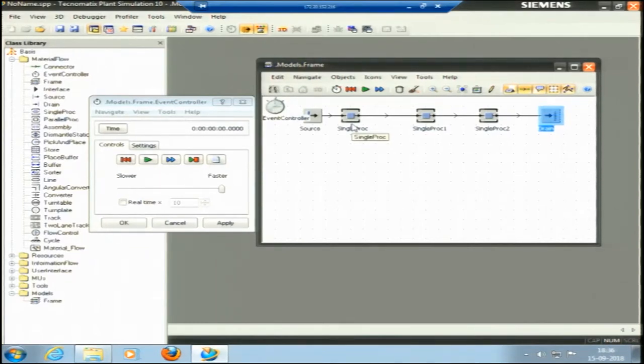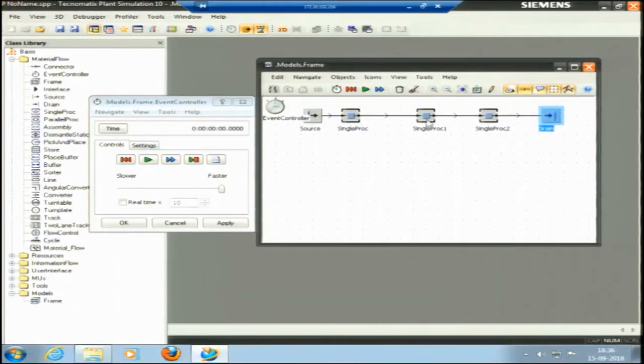This is ergonomics. If we talk about plant layout, this is work study, what is the minimum space that has to be kept. In manufacturing, the distance between two machines, other than the width of the machine, is generally kept from 0.8 meter or even more, so that the workers can move in between. This is a space in between. I have just kept it at a random location here.